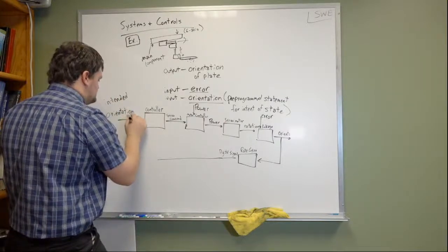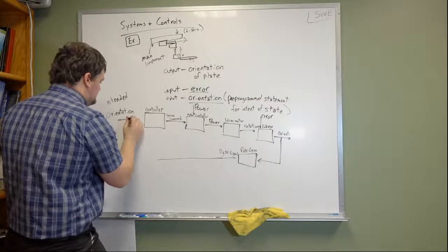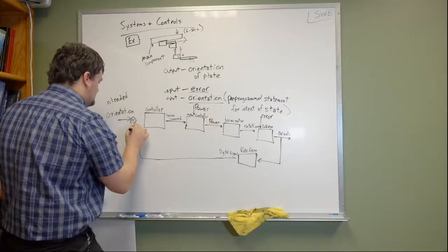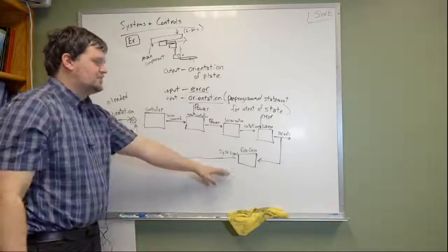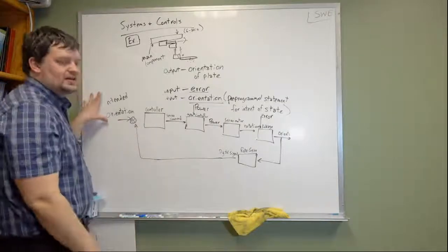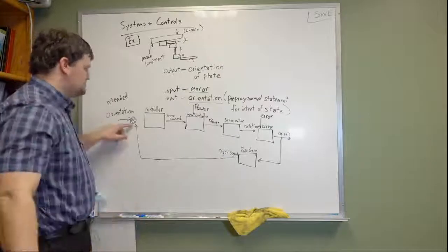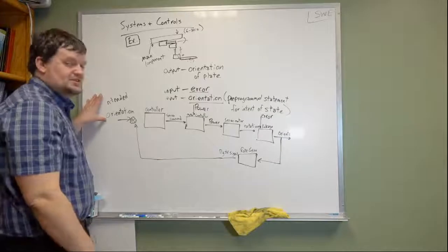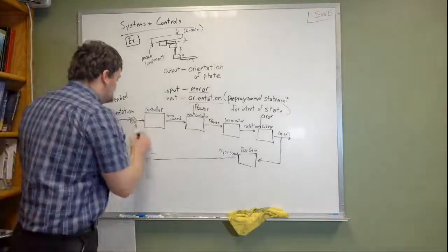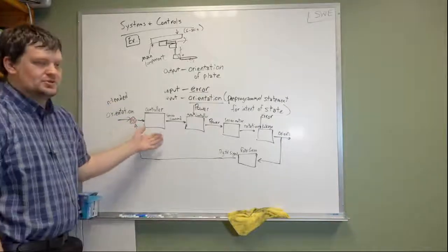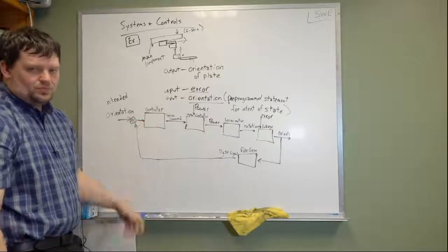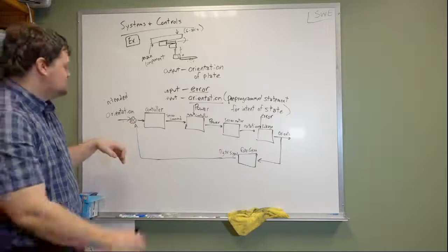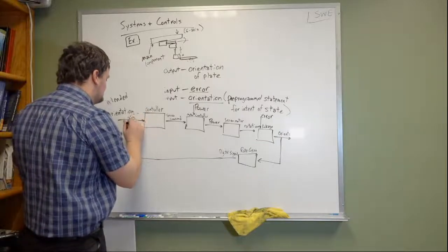I'm going to put this into a summing node where it's plus, minus. And so what happens here is we're taking the rate gyro and we're directly comparing that, where we subtract what the actual value of the orientation is as compared to the intended orientation. And then instead of just sending both of those into the controller and summing them in there, we're summing them in the controller. Yes, the summing node happens inside of the controller. This is all technically one piece.